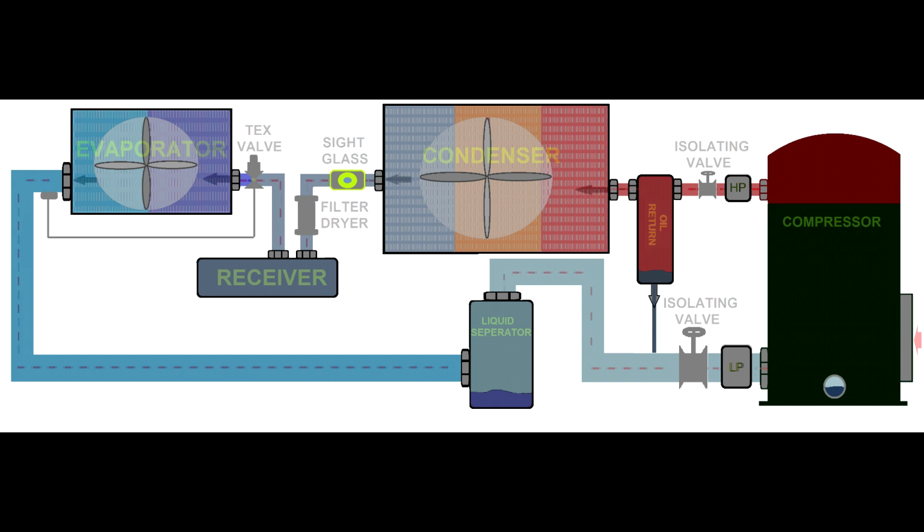I just want you to bear in mind that the compressor is cooled with the refrigerant which returns from the evaporator. So you do not have to apply too much or not enough superheat. Otherwise, you will overheat the compressor and the compressor will be damaged.